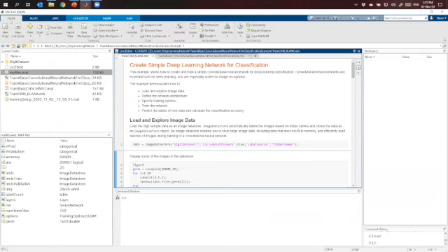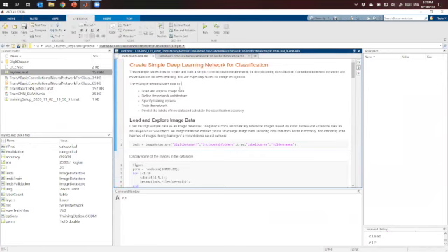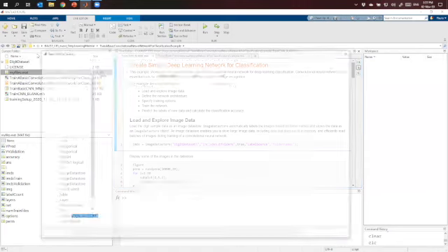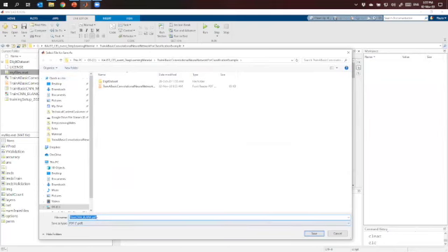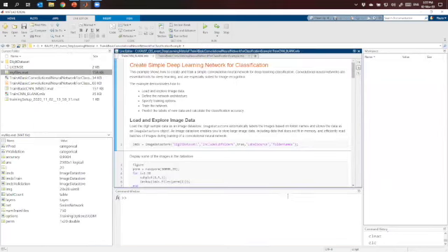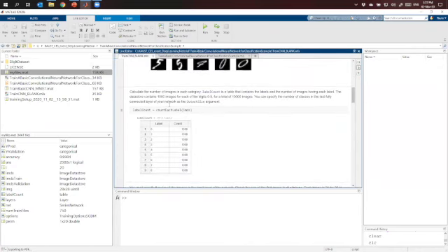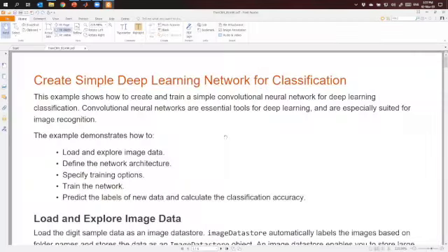So let's go to the Home tab. Now Live Editor, click here and see Save. Save as PDF. Click there, it's going to ask you if you want to save as this name? Yes, save it. And because you already ran it, you have the values there, it's going to print the PDF. So you have everything in a PDF.